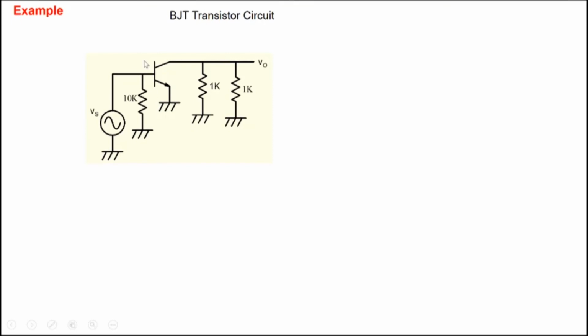But now, let's say this is an unknown entity. So what you could do is take this particular transistor and experimentally measure the H parameter representation. H11, H12, H21 and H22. So experimentally, we apply voltages and currents, and we measure output voltages or output currents, and through that we determine the parameters as ratios of voltages and currents. We've already seen how to do that.